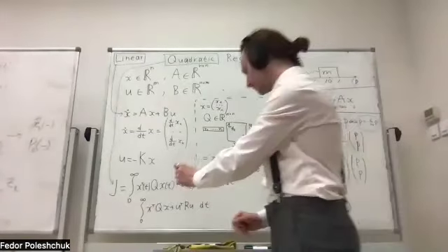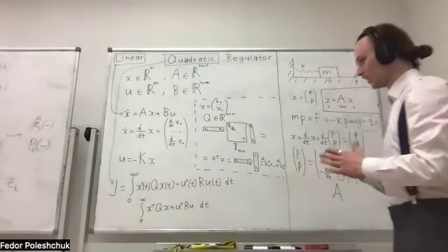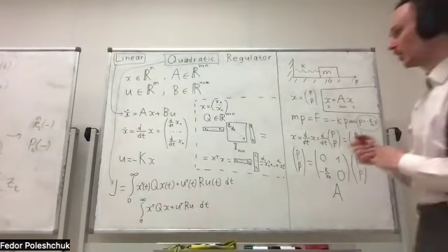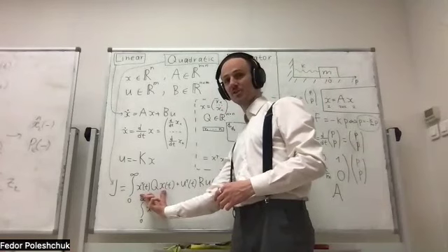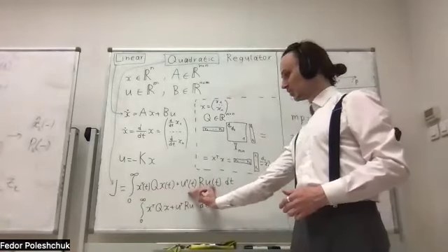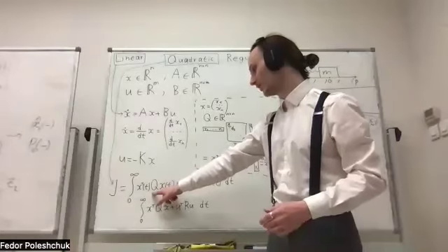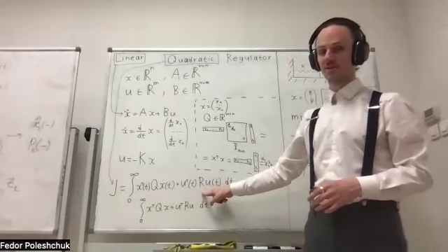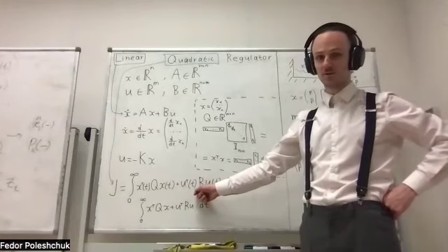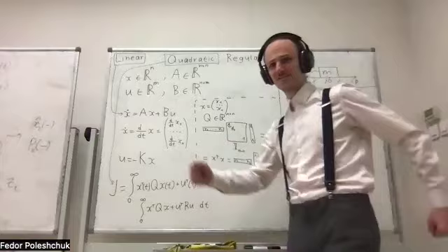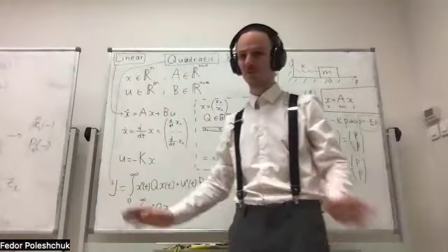So I'm saying that the relation between Q and R will influence what we value more, the deviation of the state from the desired state over time, or the control effort. If the values of Q are very big and values of R are very small, it means that we do not try to minimize the control. We're running around like crazy, and we just want to approach a certain state, no matter what.